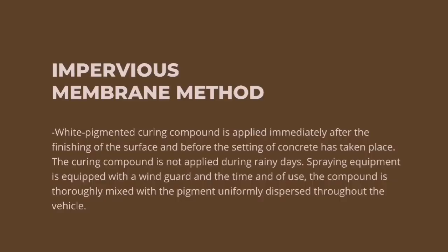So the fourth method is the impervious membrane method. White pigmented curing compound is applied immediately after the finishing of the surface and before the setting of concrete has taken place. The curing compound is not applied during rainy days. Spraying equipment is equipped with a wind guard at the time of use.